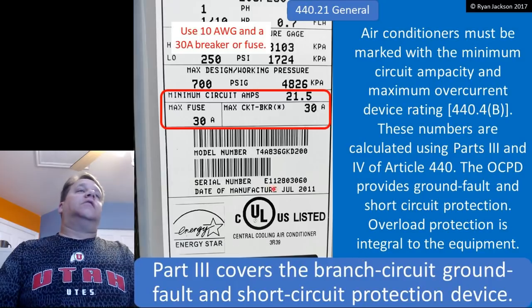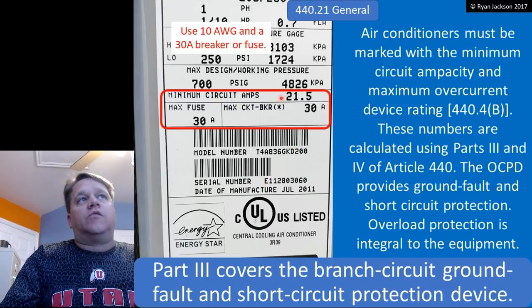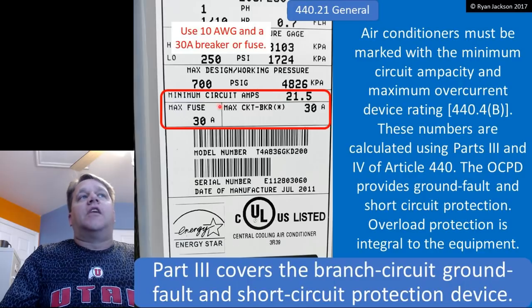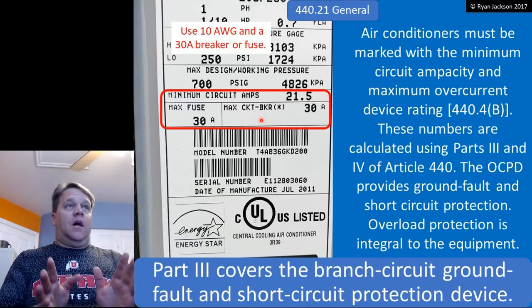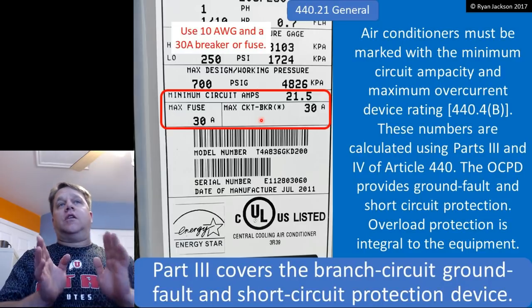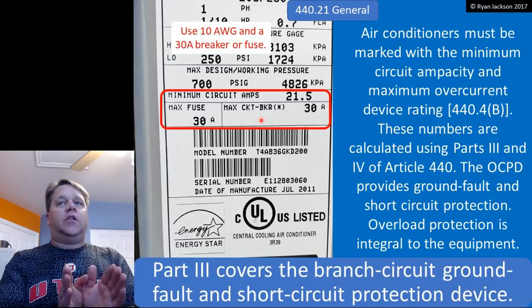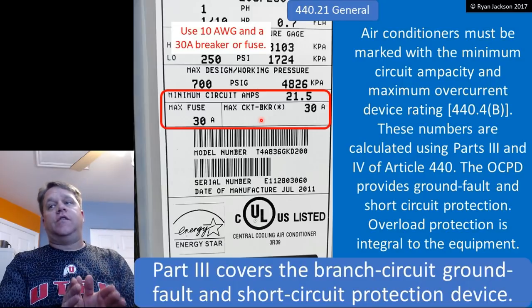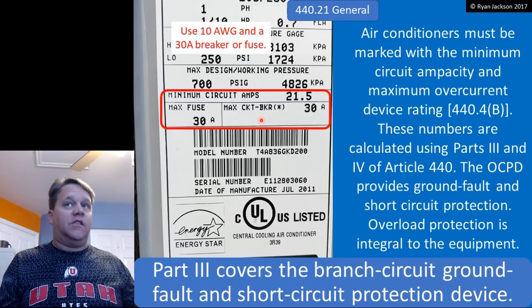All right, let's look at this piece of equipment. The minimum circuit ampacity is 21 amps. Maximum fuse is 30. Okay, now this is an easy one. I need a wire that can carry 21 amps. Now, by the way, we're going to be using the 60-degree column of Table 310.15(B)(16). We're going to assume that we're using NM cable, which is limited to the 60-degree column.